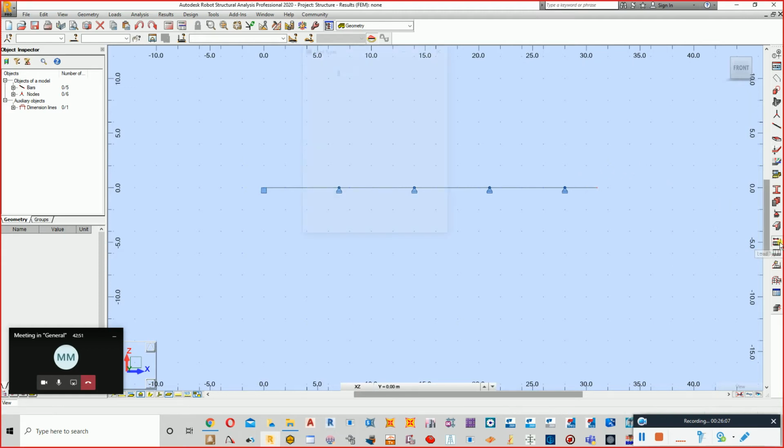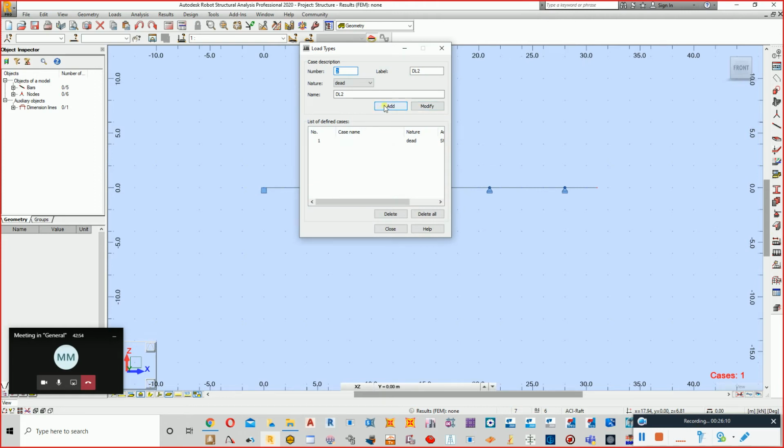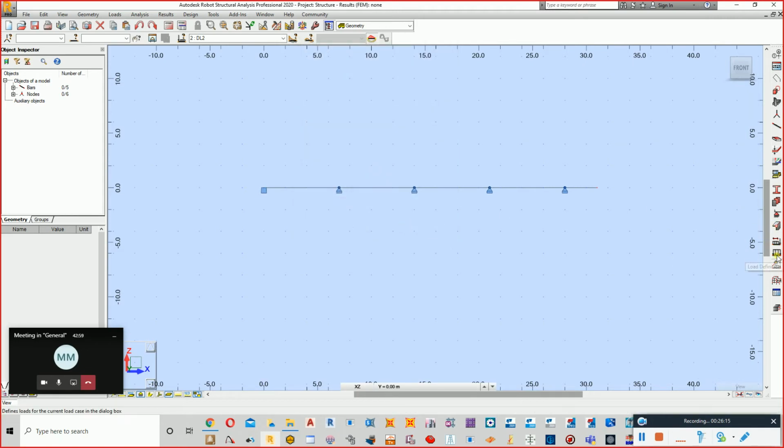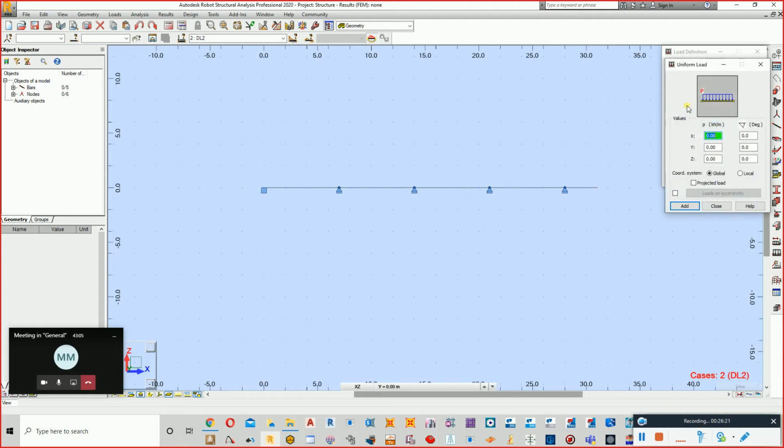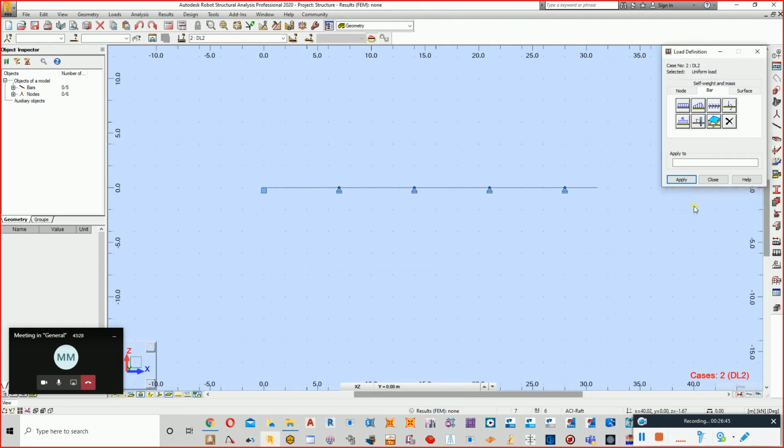After that, you can go and add the loading if you want. So we need to identify the load. Okay. And then, for example, putting a dead load, let's say, according to Robot Structural Analysis, X is horizontal, Y is horizontal, the other side, the third direction, Z is the vertical. So if we need to upload, we should go for Z. Positive is up, negative is down. So we need to go and have it down, for example, -5.